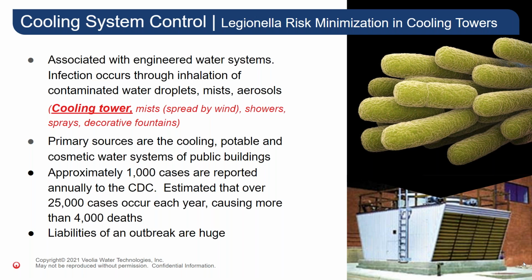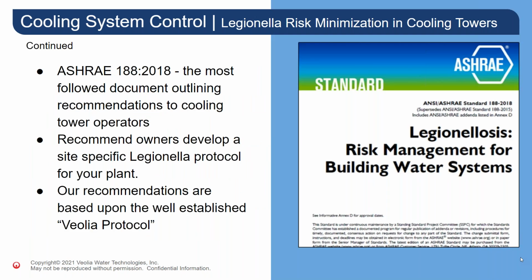This bacteria is not particularly strong, so proper treatment of the cooling water system with biocides will control Legionella as it controls the other microbes. However, due to the dangers associated with Legionella, various trade groups and the CDC have written best practice manuals with legislation likely to follow, outlining various steps that tower operators should take to minimize their risk to humans. Of note, the testing for Legionella is fairly inexpensive and readily available. We recommend testing quarterly in order to ensure this bacteria is under control, and it also helps reduce liabilities for the owner.